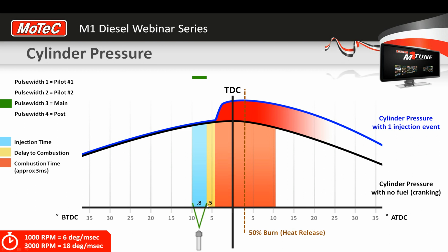So that is just not the case with the petrol. If you make your petrol engine richer, make the pulse width longer in a petrol, it doesn't affect the point at which you would light the ignition or light the fuel. The only thing that changes the decision on your ignition point is more the load or the boost, and it's not about how long the pulse width is.